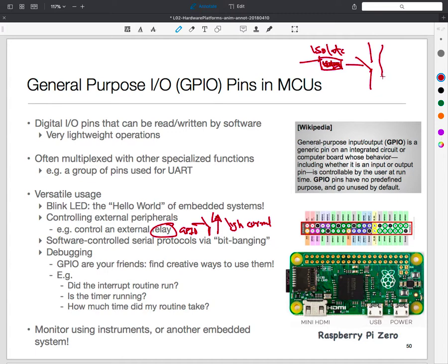Okay, so this is high voltage, and this side is low voltage, and you don't want them to be mixed with each other. So what optical isolation does is it uses a phototransistor, so that on the left hand side you are going to be driving an LED, and its optical output is going to turn the transistor on and off, and the high voltage cannot jump that way.